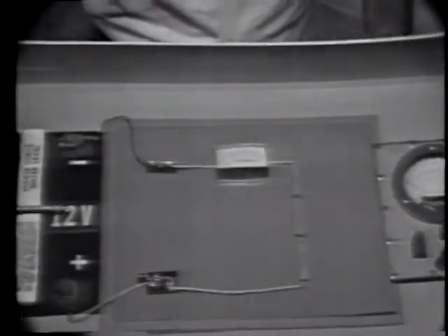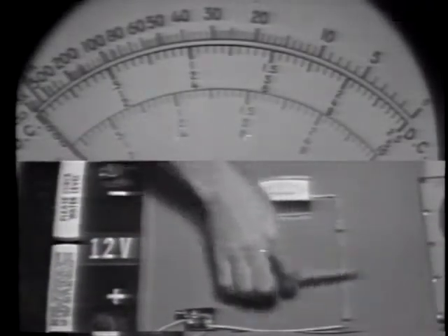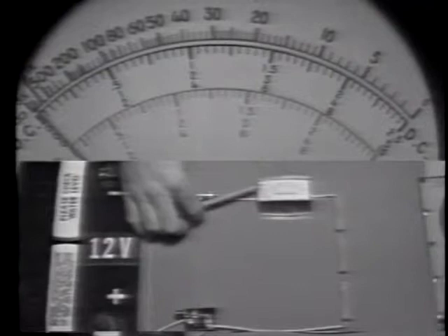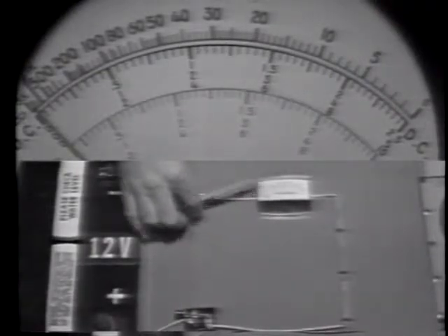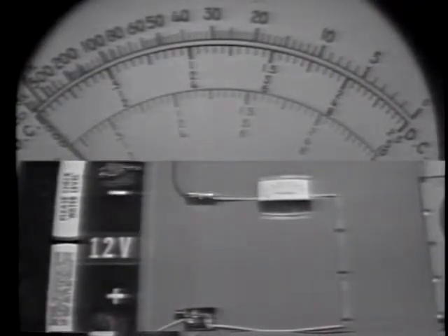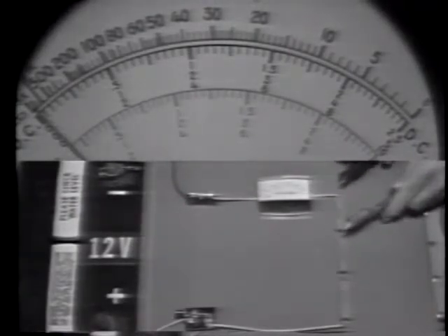Well, let's find out what the voltages are in this circuit. To do that, we'll use the PSM6 as a voltmeter. The function switch is on DC volts, and we'll use a range of 10. We'll use the 10-volt range because the applied voltage is 12 volts, and this 12 volts will be distributed around the circuit as long as a reasonable amount of current is flowing. Okay, let's check across each resistor.